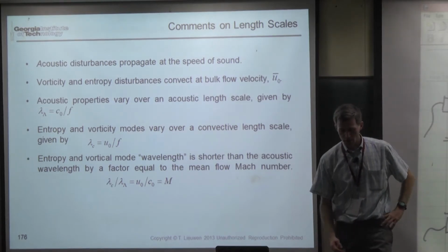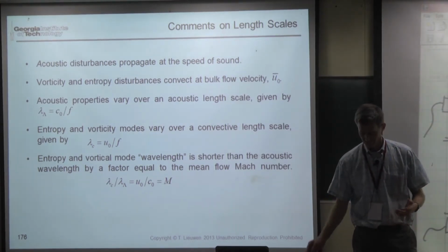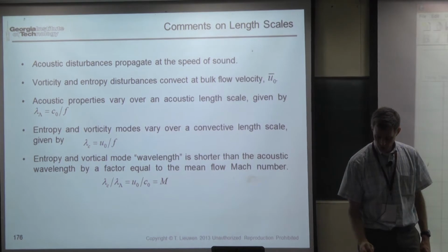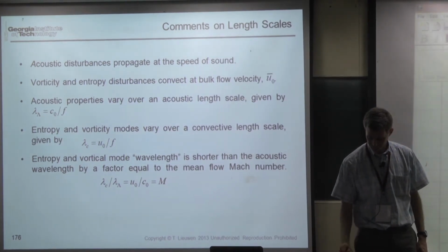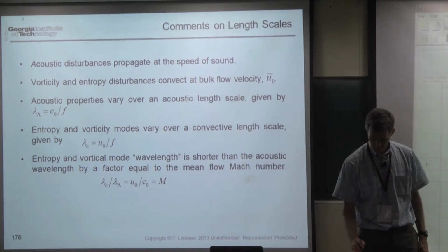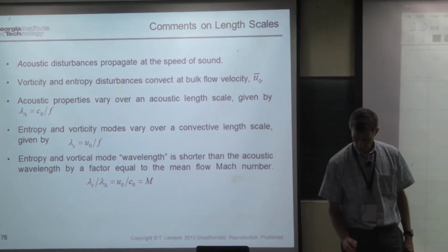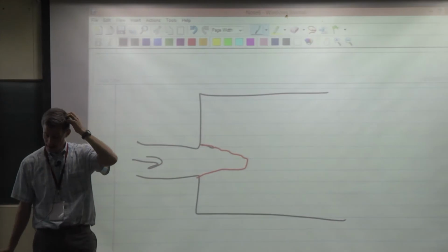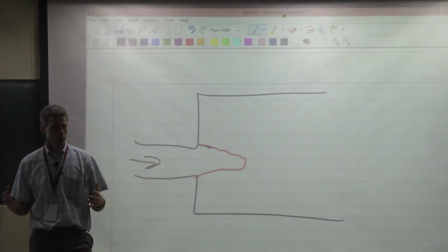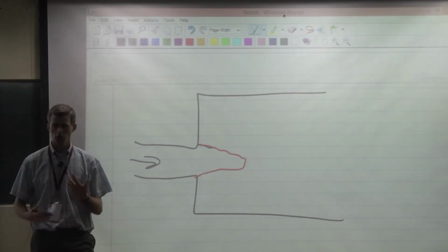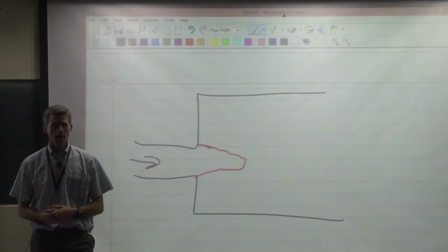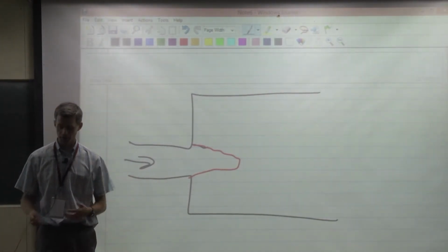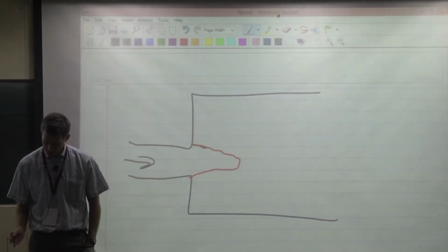So this actually turns out to have lots of important implications for problems in different fields, but I'll give you one example. Let's suppose that I'm trying to understand, I'm going to draw a flame. Flow is going left to right. I want to understand how this flame is behaving during a combustion instability. During this combustion instability, there's acoustic waves bouncing around, all right? And those acoustic waves are exciting vortical disturbances, all right? So I'll have both acoustic velocity disturbances and vortical velocity disturbances coexisting.